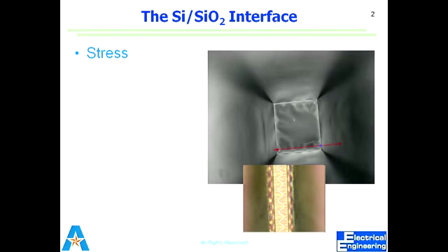So it's actually TCE, that is thermal coefficient of expansion. The change in the thermal coefficient of expansion causes that residual stress. So when you cool down or heat up your wafer, this stress should come into account, because silicon dioxide has 5 times higher thermal coefficient of expansion as compared to silicon. So due to that difference, there would be a residual stress.